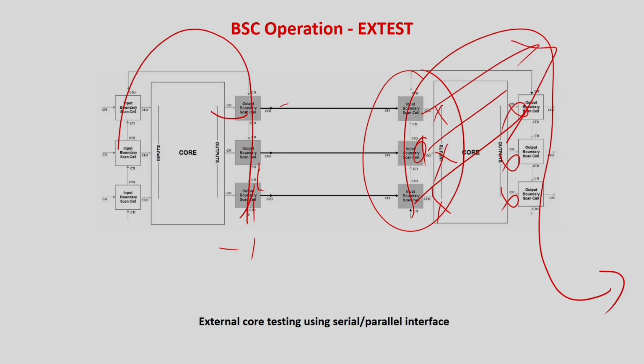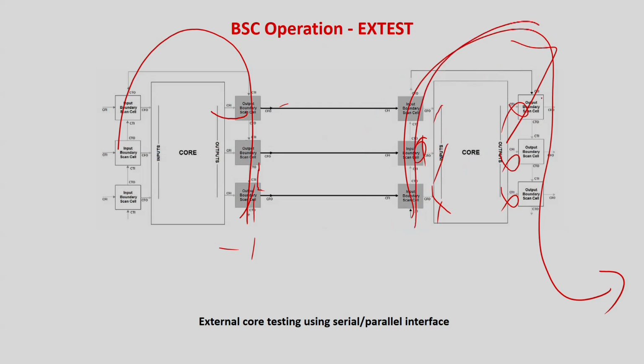This depends on what speed and what overhead you give for the TAM. Here the TAM overhead will be very high because you have to give parallel access. But if you do not want parallel access, that's also fine. You can take the values at the scan output and do the test. So EXTEST is very important.